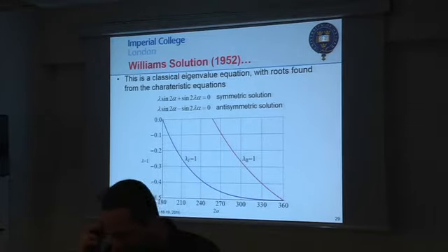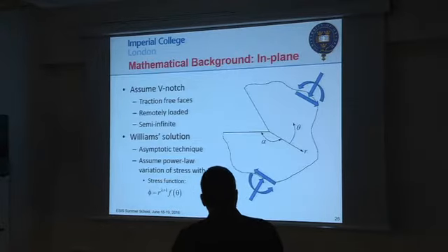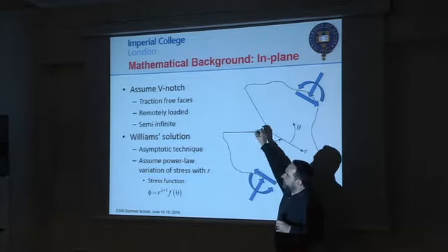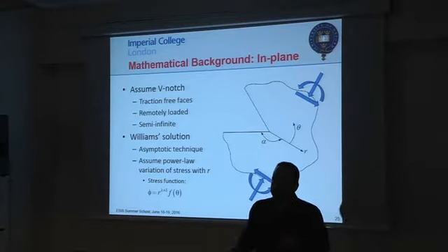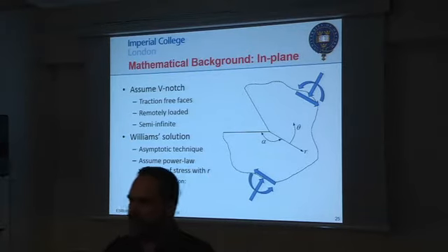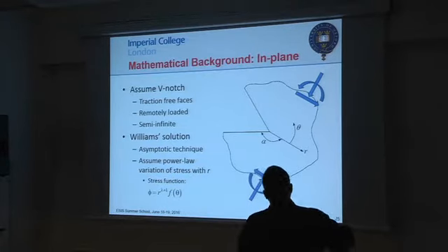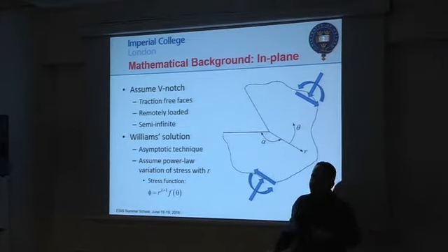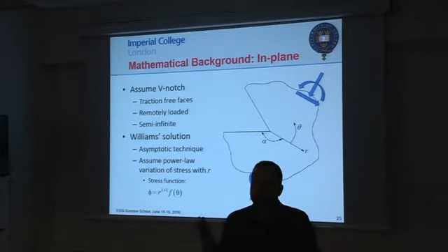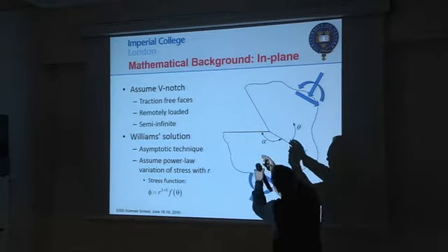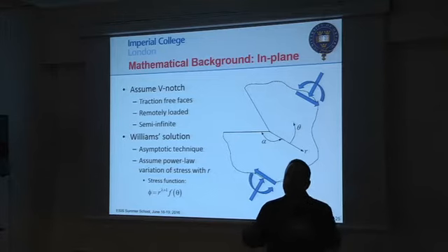What I'm trying to explain mathematically is that if you go back to here, if you have a crack, so if you make this notch angle very small, and you look at loading the crack this way and loading the crack in mode 2, mode 1 and mode 2 give you a singular solution, and the magnitude of the singularity is the same. The moment you expand the notch and make the notch wider and wider, that is not the case.